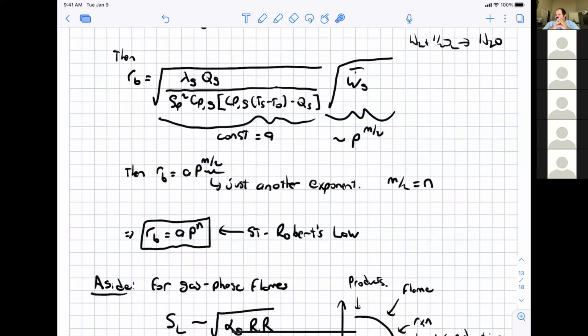If the interfacial energy balance criteria is met, that is, your assumed burning rate is matched, or the gas phase flame using your assumed burning rate is properly mated to the condensed phase region of the propellant.